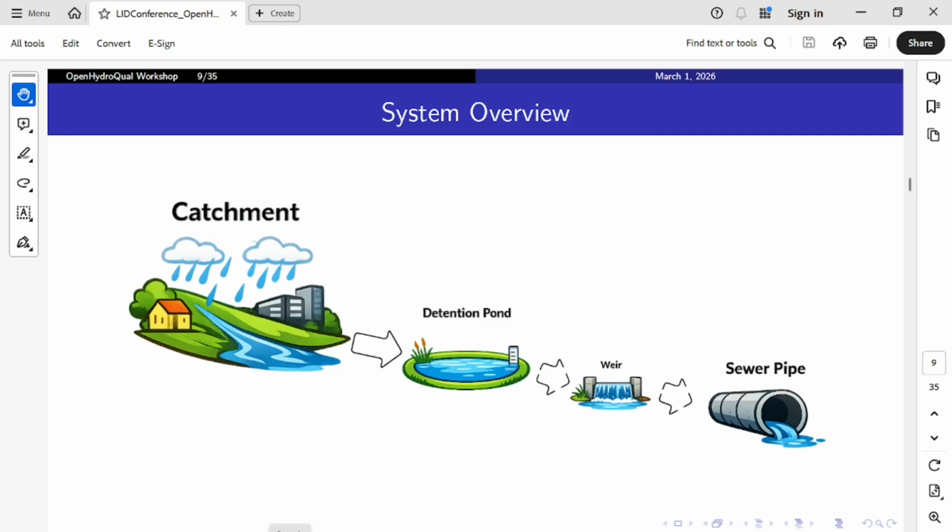If I want to do that, then I can consider this my boundary condition, which means I'm going to use this thing called a fixed head boundary. A fixed head boundary is something whose storage can change, but its head does not change. So it's like a large body of receiving water. If you discharge into a lake or an ocean, it can probably be represented as a fixed head boundary, because its head is not significantly affected by how much water you discharge into it.